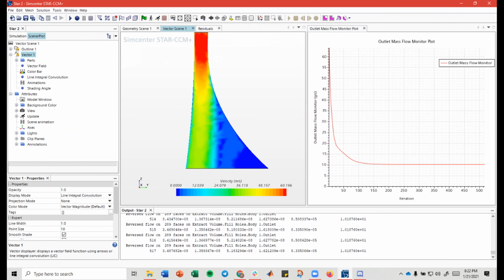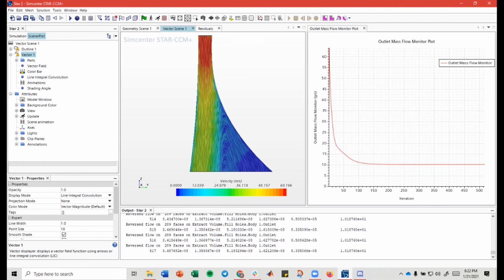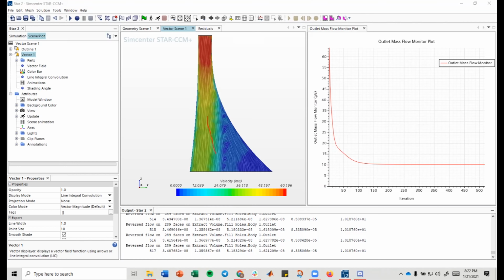So right off the bat, we can come up with a couple of solutions to this. We could create a vane right here, create another vane right here, which basically will direct this airflow. Instead of just going straight down, it'll go through this channel. Same with the airflow here. Instead of just going straight down and detaching, it'll be forced to go through this channel. And we could reduce the amount of flow separation going on over here pretty significantly.